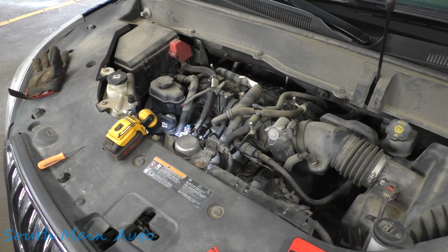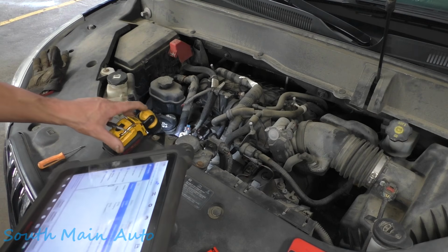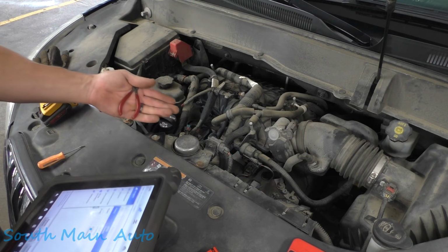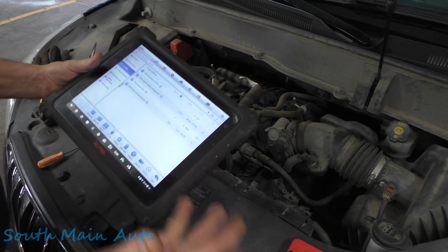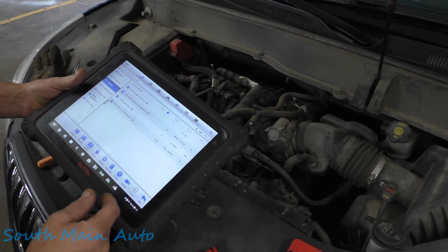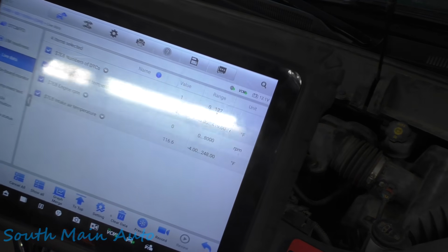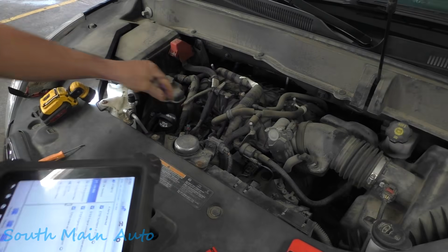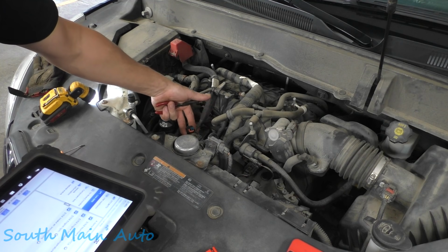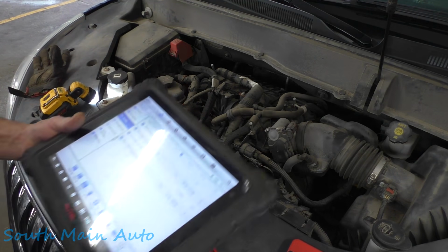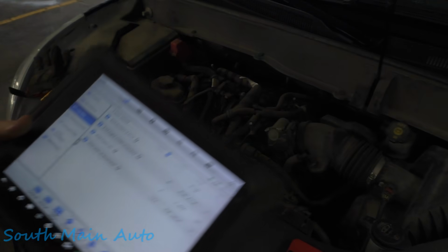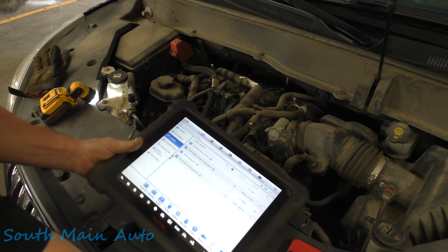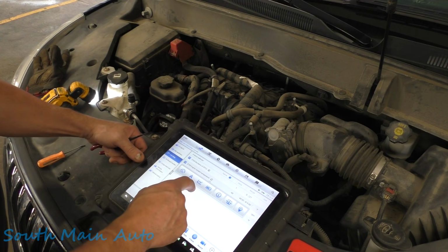So this could bring up the question just real quick, we'll address it: how do we know it's the sensor? Well, I guess to be definitive, we don't. We can assume, but we can do a quick circuit check on it. So right here, I've unplugged the coolant sensor. Kind of a pain to get to. It was toasty too. I had to put on a glove. So we're at minus 40. That's what we expect to see. And then when we short it, it should go to around 300.